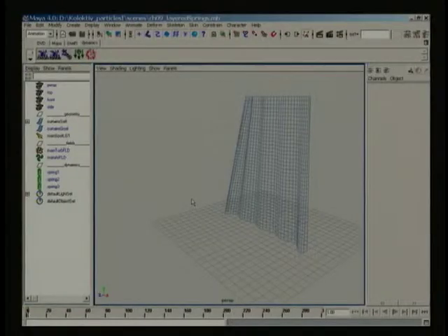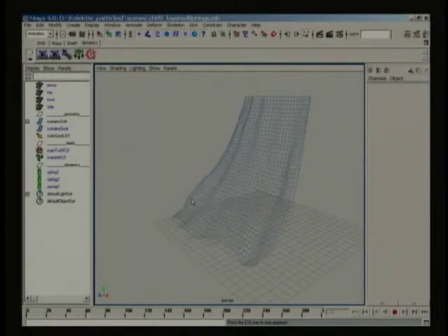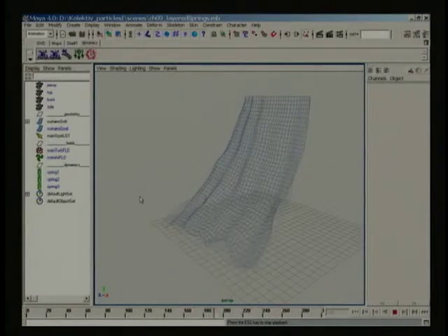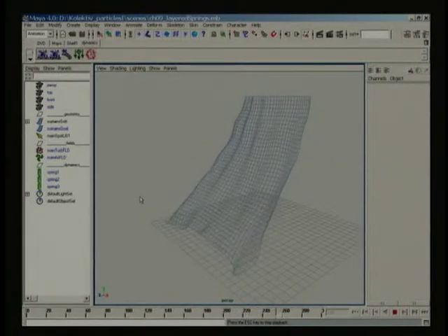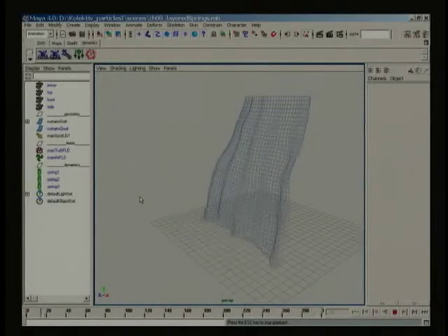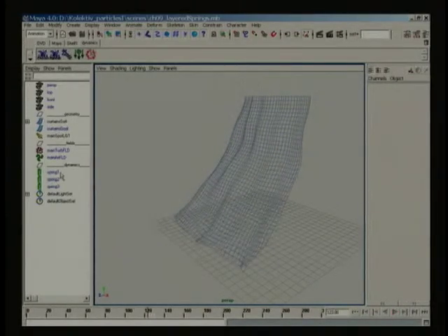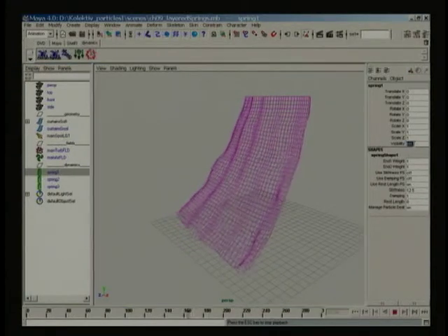I've found the wireframe spring creation method to be superior to the other two, min-max and all. However, each option still has its ideal uses. If you need to conserve the volume of a softbody object, the min-max method is essential, as you can set up an internal spring structure that spans one side of the object to the other.